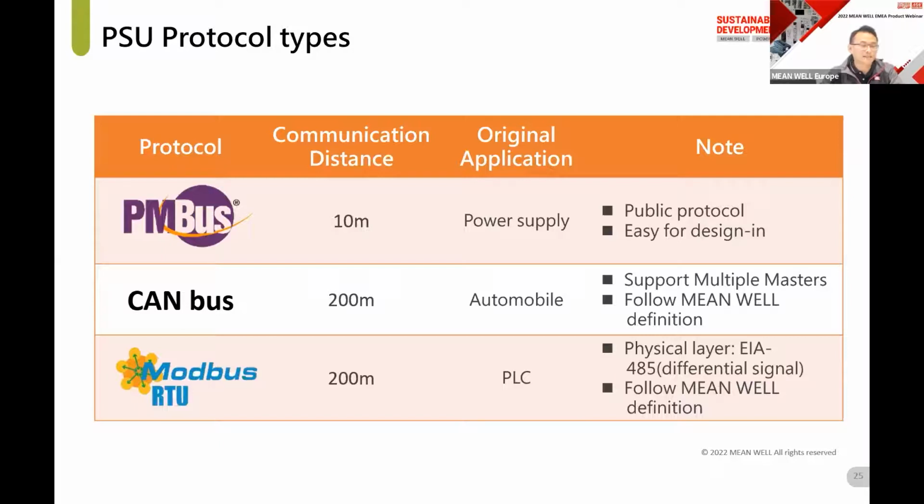Modbus is a data communication protocol for use with programmable logic controllers, which are PLCs. Modbus is very popular in the industrial environment because it is openly published and royalty-free. It was developed for industrial applications. It's relatively easy to deploy and maintain compared with other standards.